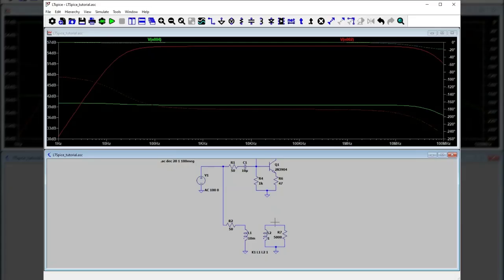But what are we looking at here? So we have this source, a 50 ohm resistor, and we want to build a transformer that transforms 50 ohms up to 5,000 ohms. So that's a 100 to 1 impedance transformation. 50 to 5,000, 100 times. What does it take to do that in the transformer? An ideal transformer takes a 10 to 1 turns ratio.